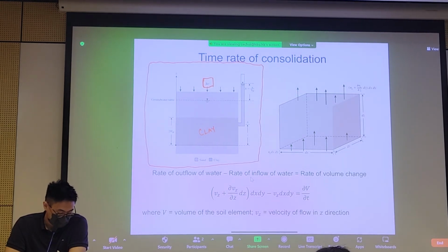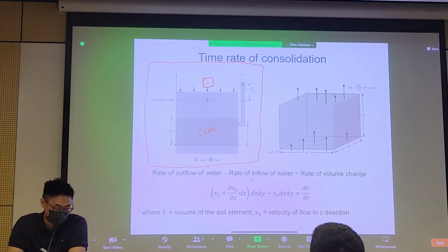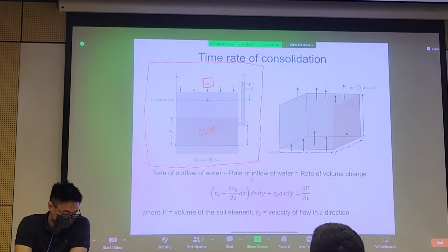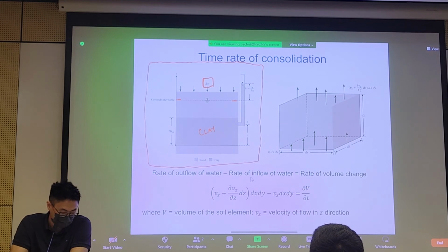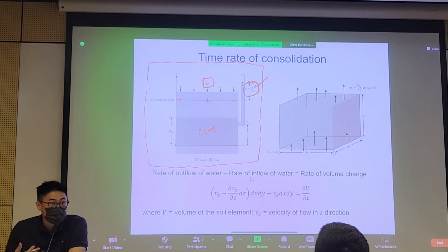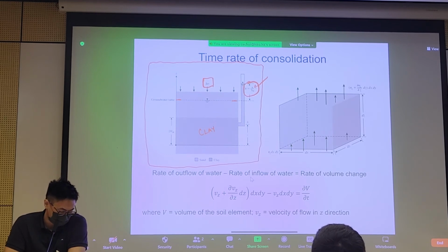And by applying this total stress, we do have some excess pore pressure generated, right? Because you can see that the groundwater table is initially here, right? And assuming that this is a hydrostatic groundwater table, by applying a load, we've generated some increase or some excess pore pressure. And this is the general expression for converting head to pressure, right? If we want pore pressure in units of kPa, we just multiply head in terms of length with the unit weight of water. So that's our excess pore pressure.